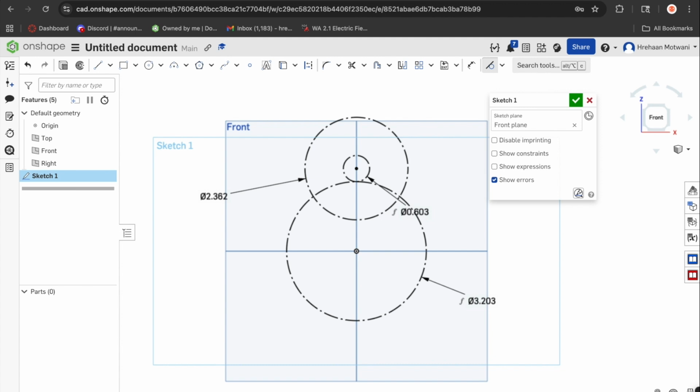And then you're going to have to put mounting holes here for the motor, and then the bearing hole here for the Thunder Hex for the gear. So starting with the bearing hole. Bearing holes are 1.125 inches, and then you have to add tolerance for when it's being manufactured.